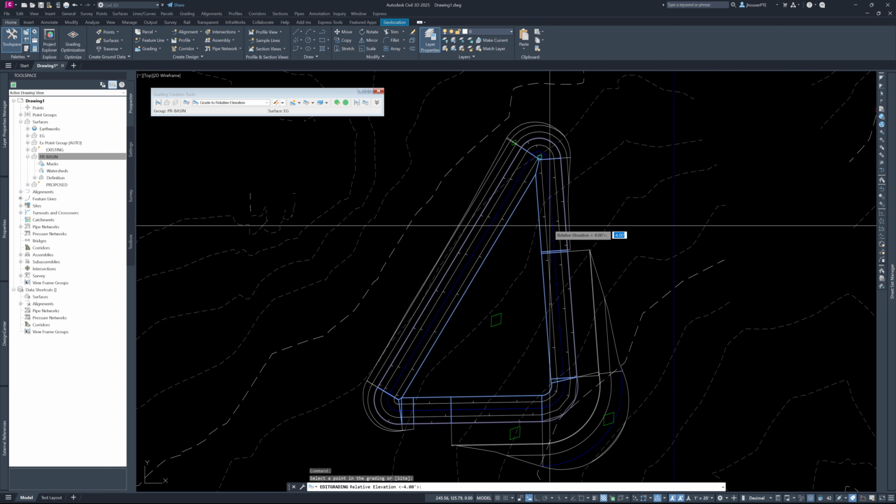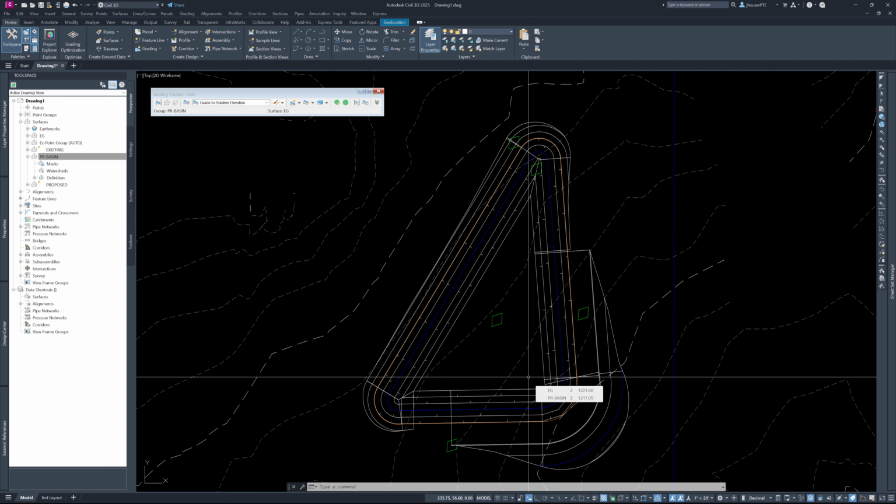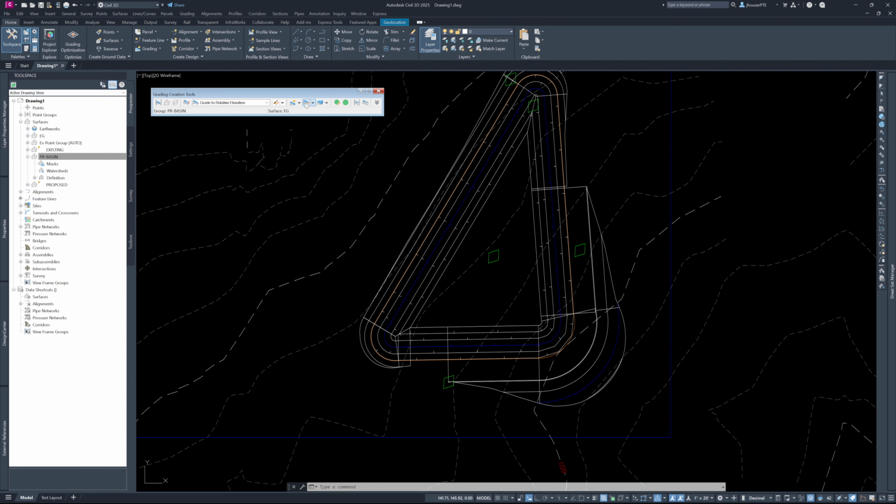So now we are at, let's see, what is it? Oh, there we go. Our basin elevation's at 1217.05. That's too low to get a pipe out. So that won't work. So that's a good option there to kind of look at that and say, okay, this is how I can adjust this. Back to a -4, slope 3:1, and that will take that back out.